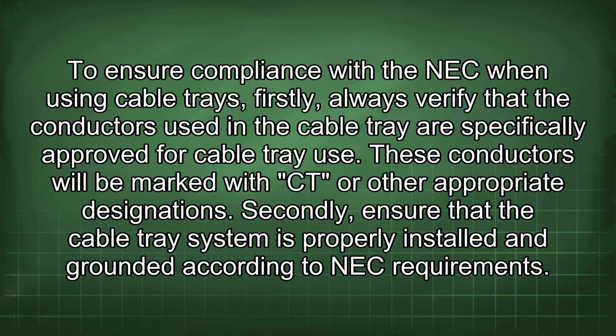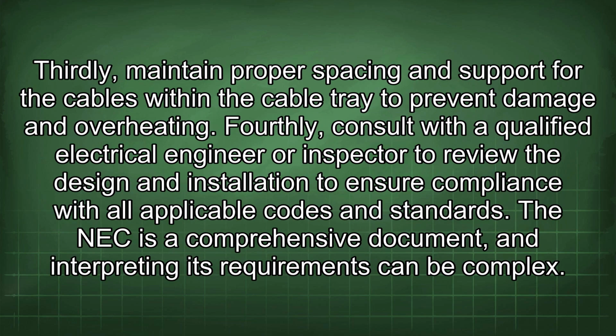To ensure compliance with the NEC when using cable trays, firstly, always verify that the conductors used in the cable tray are specifically approved for cable tray use. These conductors will be marked with CT or other appropriate designations. Secondly, ensure that the cable tray system is properly installed and grounded according to NEC requirements. Thirdly, maintain proper spacing and support for the cables within the cable tray to prevent damage and overheating.